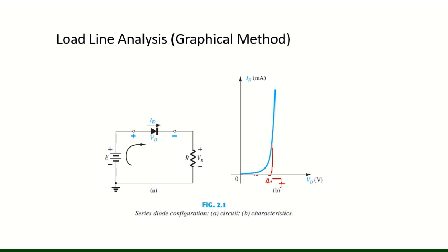At 0.3 the current flow across the diode will be like this. It is in milliampere, but for example, let it be 1 milliampere. At 0.3 or 0.2, just as an example, I write here 1 milliampere, but at 0.7 volts the maximum current will flow through the diode. So this is a 2D plot, in which I have shown you the voltage. When the voltage of 0.7 is applied to the diode, it will allow the maximum current to pass through it.